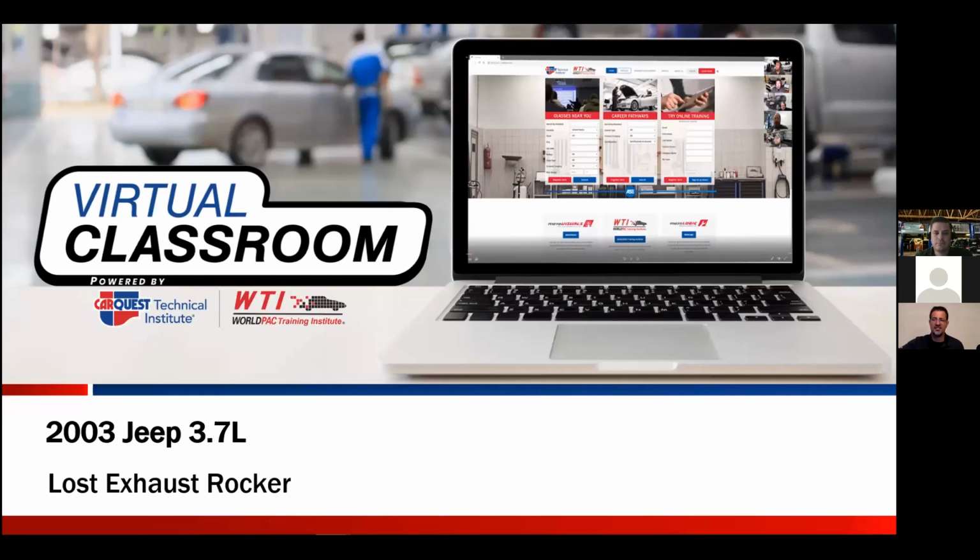Now, as soon as I tell you it's an 03 Jeep with a 3.7 liter engine, you guys probably already know what's wrong with it, and you'll want to move on to the next case study. This one lost an exhaust rocker. It spit one out.